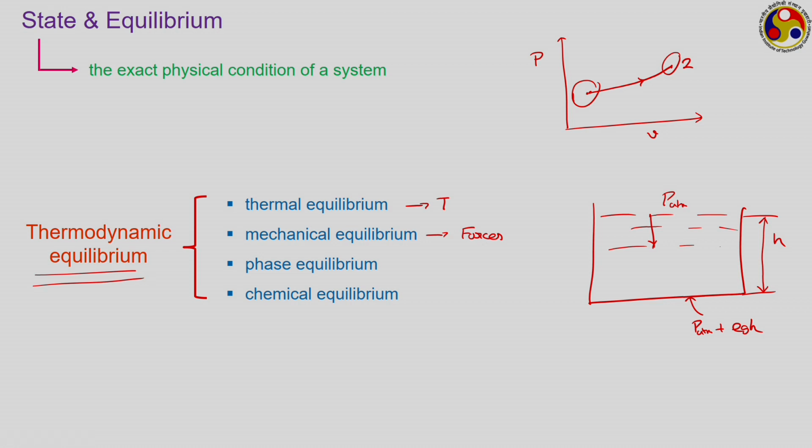and that is where the difference with heat transfer comes into the picture. If a system is in thermodynamic equilibrium, then it is also in thermal equilibrium, that is, the temperature everywhere in the system is constant, and if the temperature is constant everywhere in the system, then there will be no heat transfer, because the primary requirement for heat transfer is a difference in temperature. Therefore, if a system is in perfect thermodynamic equilibrium or at least in thermal equilibrium, there will be no heat transfer at all. In order to have heat transfer, we first need to have a non-equilibrium,